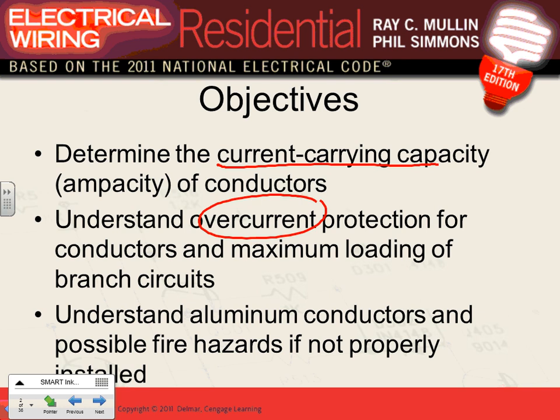Aluminum. When you have aluminum conductors, guys, we'll talk a few things. I don't focus too much on this because it's electrician work, but we'll touch on how you terminate aluminum conductors. We all know if you terminate aluminum conductors, the lugs have to be rated for aluminum, right? Number one. Number two, if you have aluminum and copper, you can't put them under the same lug. You have to have a lug specialized for aluminum and copper. They put them one on one side, one on the other side, and they torque them.